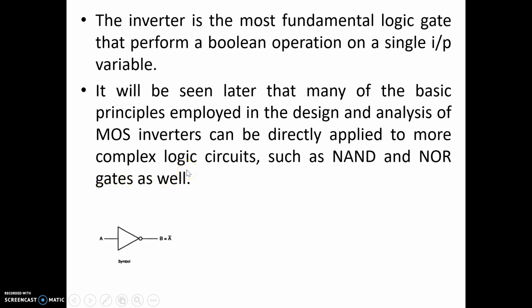So in the MOS inverter, we calculate VIL, VIH, VOL, VOH and VTH. So we calculate all 5 parameters, and all 5 parameters can be directly calculated for the complex logic circuits such as NAND gate and NOR gate.